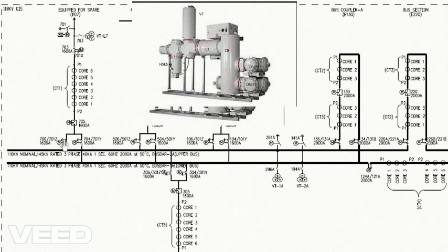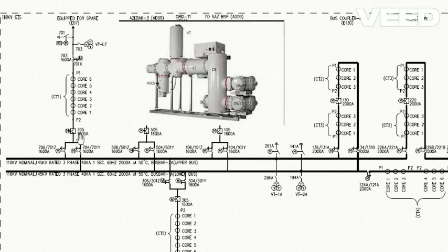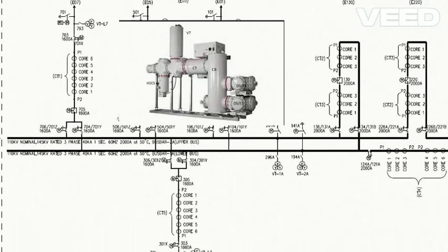Both of them cannot be closed together under normal conditions. But in maintenance conditions or in some special conditions, you can do it. However, once your prerequisites for circuit breakers are met according to the interlocking scheme, you can easily close the circuit breaker. The same philosophy will be followed for all other bays.